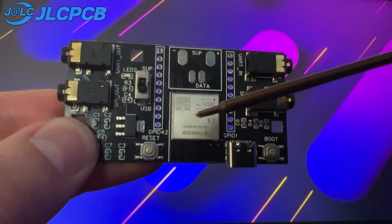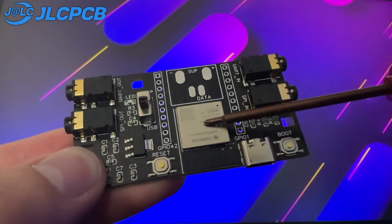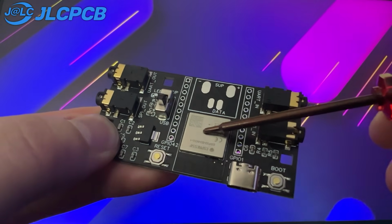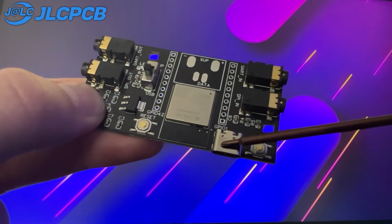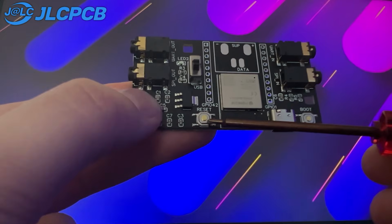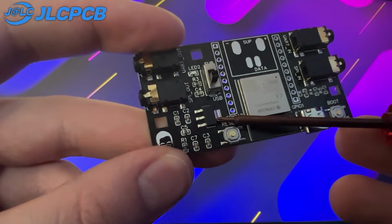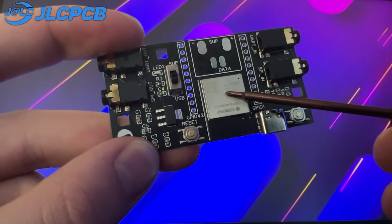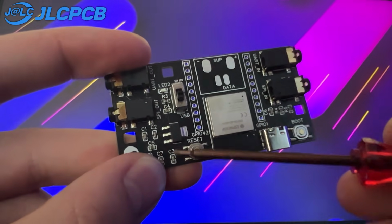As you can see, I'm using the latest gen ESP32S3 system on a chip, which has a ton of built-in features like Wi-Fi and Bluetooth. Very cool. If you want to see why this microcontroller is so awesome, be sure to check out my last video. This is a USB-C port for both programming as well as power. This is a boot button to get to the bootloader for programming, and a reset button that does what reset buttons do, obviously. And we have here a 5 volt to 3.3 volt regulator, because the ESP32 takes a 3.3 volt power signal, but the USB port as well as our power supply are both 5 volts. So we need this regulator.